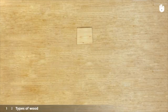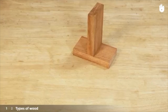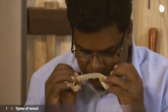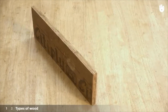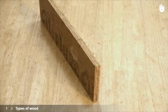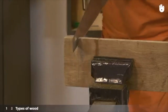Softwoods such as pine and red cedar are lighter and generally easier to work with. They grow much faster and are lower in cost, mostly being used for construction purposes. Pinewood is extremely easy to work with and exudes a sweet aroma. Apart from solid timber, you also have manufactured boards, such as plywood or MDF, which are more affordable but aesthetically less appealing. Plywood is made by gluing together thin layers of wood veneer. The grain in each layer of plywood runs perpendicular to the previous one, making it structurally strong.